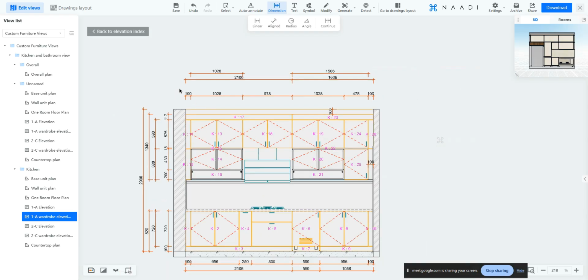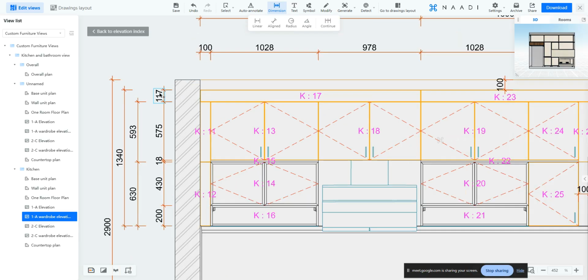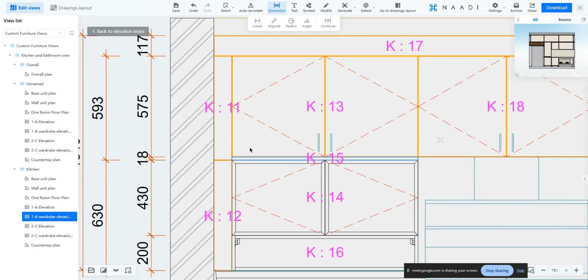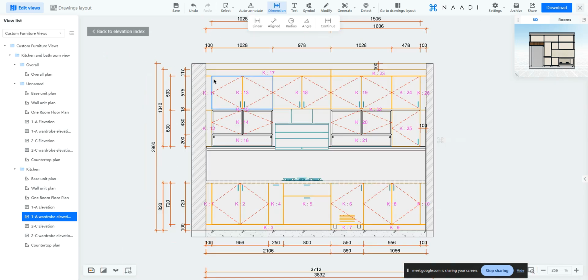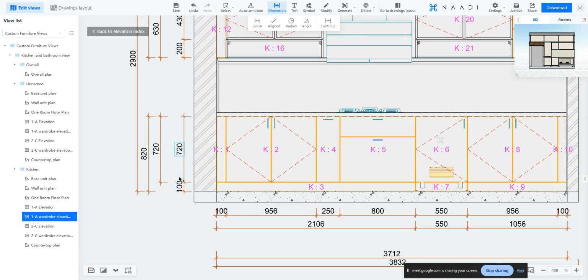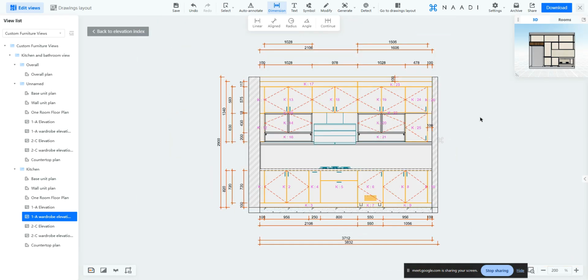Okay, similarly, this is your width. This horizontal dimension is always about your width in your elevations, right? Similarly, this vertical dimension is about your height. You should already be aware. So this is the filler height, the loft cabinet height, and here I've placed a fixed panel between the wall and loft cabinet, so there is the panel thickness, the height of this wall cabinet, and the height of this part. Similarly for the base cabinet, the height of this one and the height of this. So all the dimensions you need for your cabinets are automatically mentioned here. You can directly take it forward.